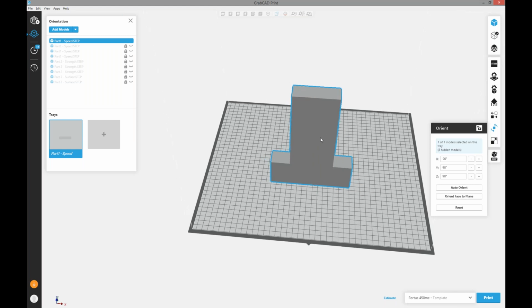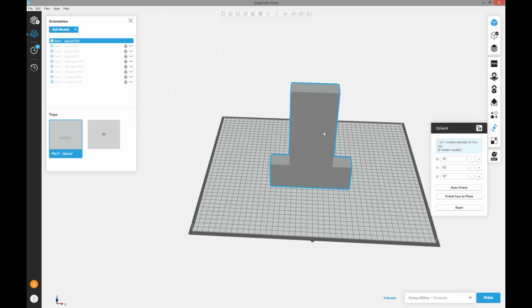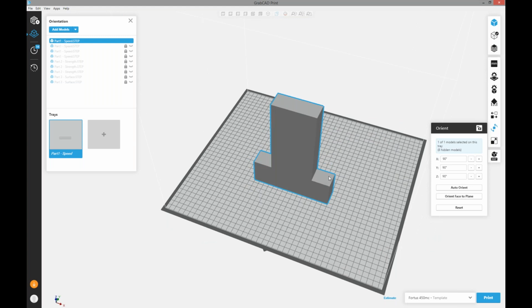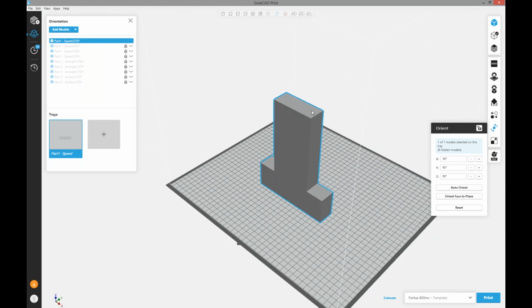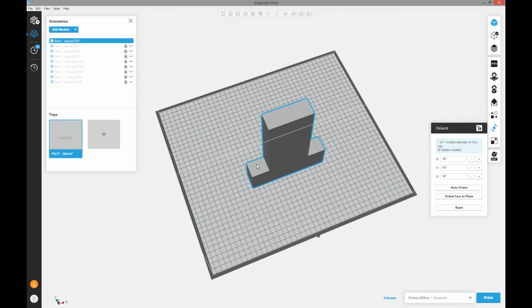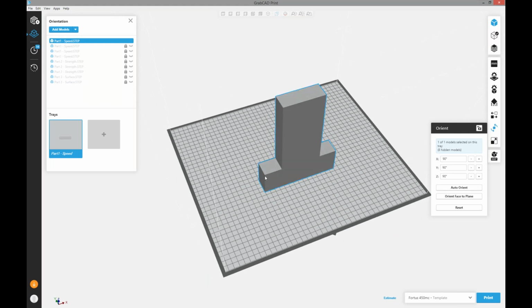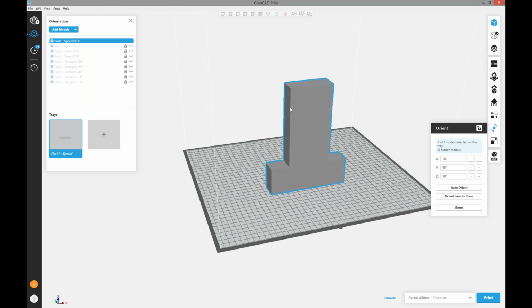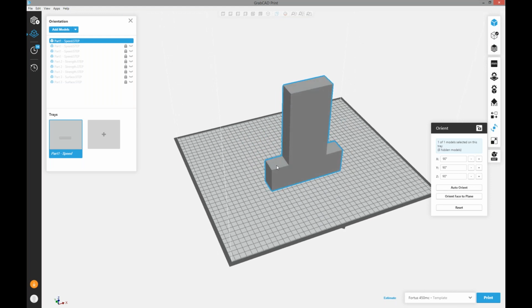So basically, the software, and this probably could answer the question from the audience, will try to look for angles which will be supported and orient the part to minimize the support structures being built on the build plate, which also means if we have supported structure, then it will be printed longer. So in some way it can be said as speed, but actually in the background the software would check for any support structures being built and try to get rid of them.